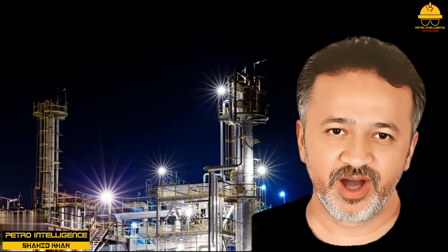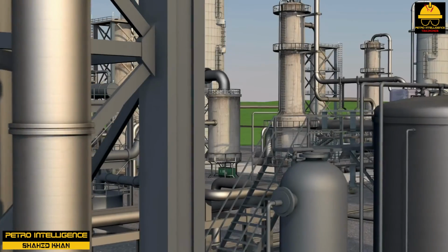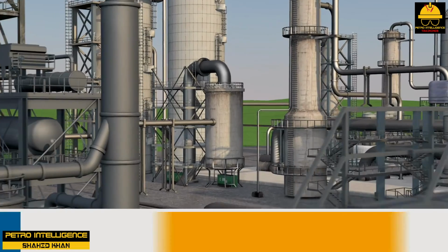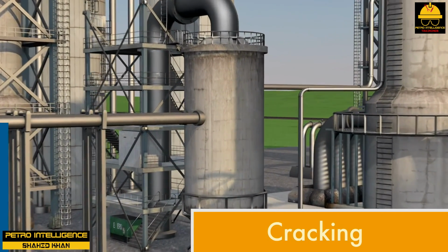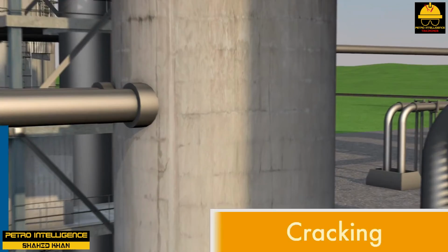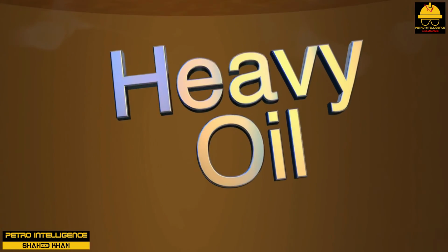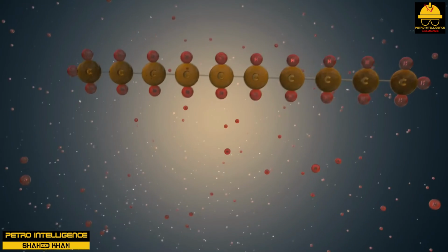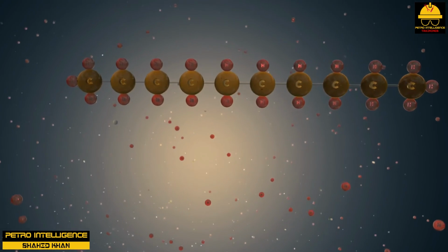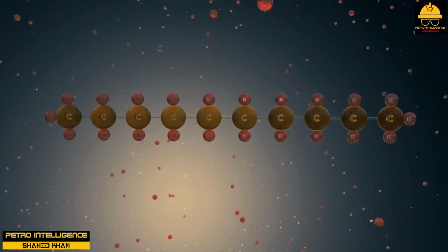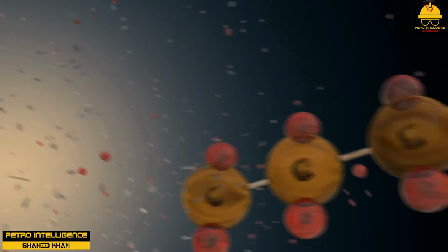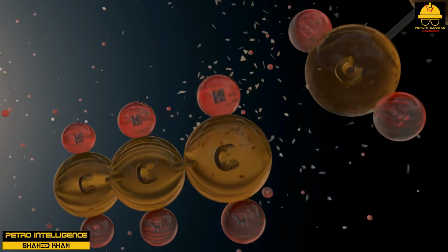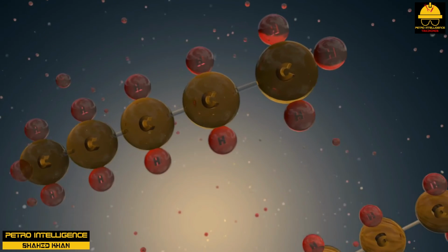Fluid catalytic cracking. Crude oil comes into a refinery and is processed in an atmospheric pipe still. The side stream of the pipe still is rich with light gas oil. Fluid catalytic cracking or CAT cracking units take this gas oil and split it into smaller, more useful molecules. During operation, fluid catalytic cracking units use a catalyst regenerator, a fluidized bed reactor, and a fractionation tower.